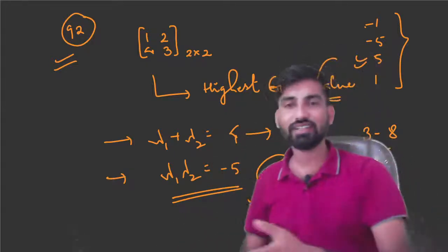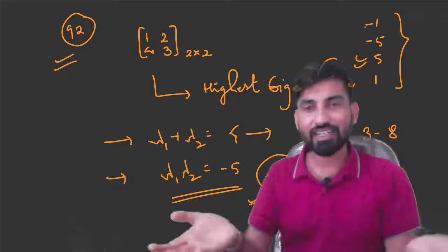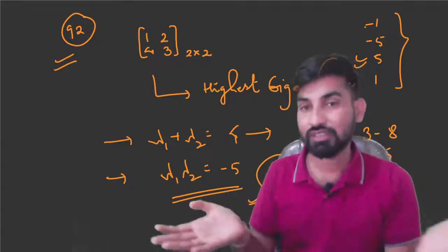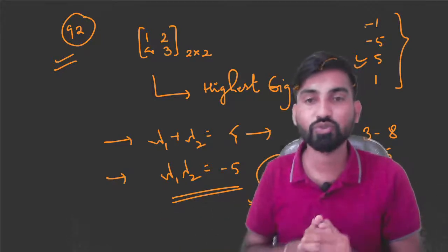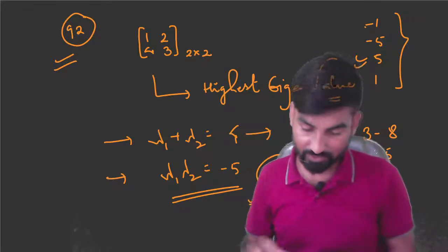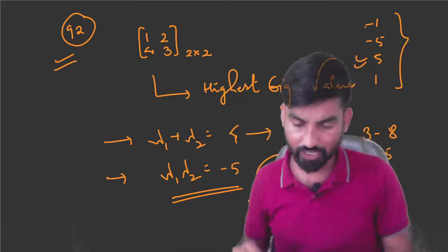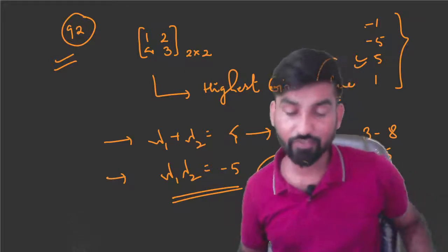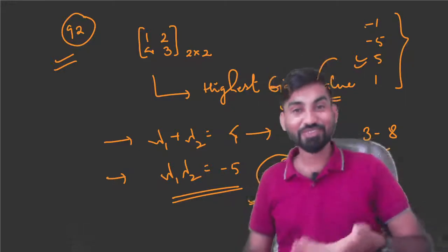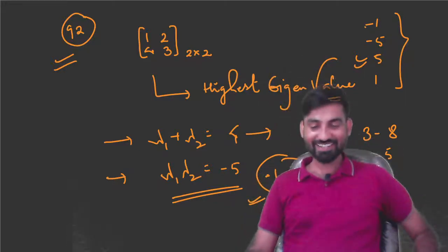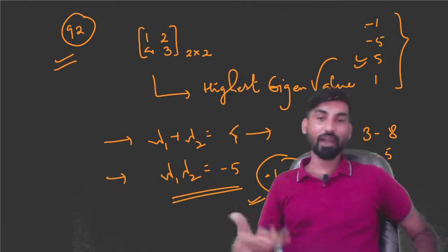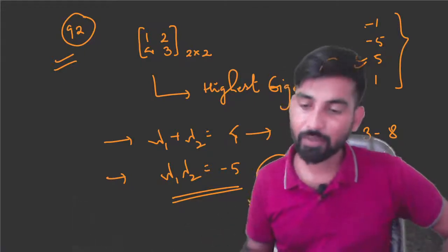In the ESE you can see a question where some sinusoidal signal is given, and they are asking the RMS value. So maximum value upon root 2, very easy question. And one question in fact I was fascinated with was from diode only, the rectifier. A half wave rectifier was given, and they asked about the DC voltage across the diode. This question was very easy, and you have to answer in approximation. So minus Vm by pi will be the answer, approximate.